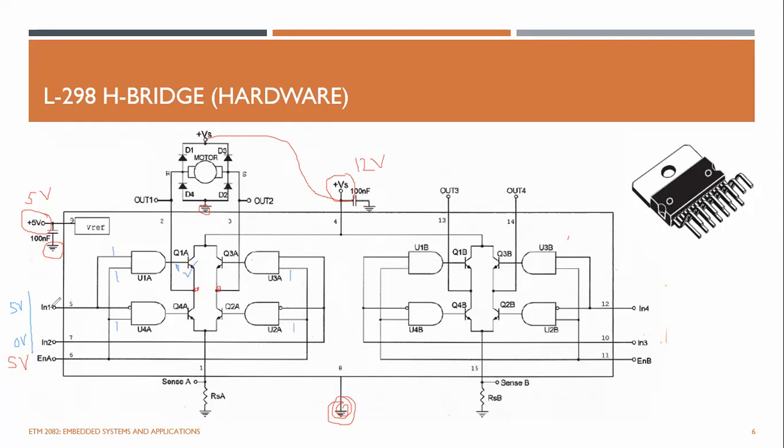And here you can see this is logic 1, but there's a NOT gate, which means this is 0. And 0 and 1 is 0. This transistor is turned off. Here, this is 1 and this is 1, but this is a NOT gate, and this is 0, so the output is 0, and this transistor is turned on.